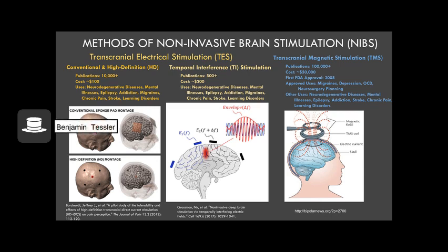The conventional method uses square sponge electrodes to inject current across the head from an injecting current electrode lead and a return current electrode lead, which would have equal but opposite strengths at the electrode surface, while the high definition approach uses much smaller electrodes and multiple electrodes for the return current electrodes, so that the return currents are more diffused and are effectively reduced.